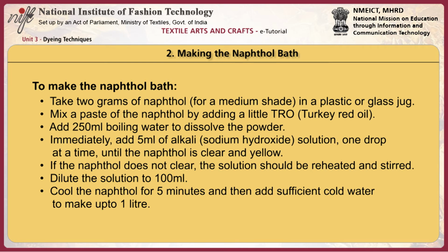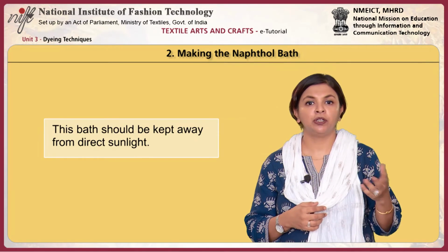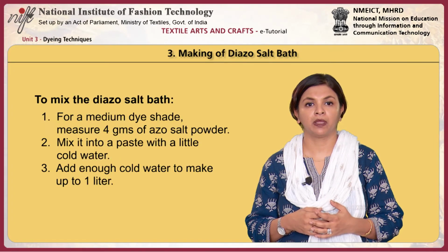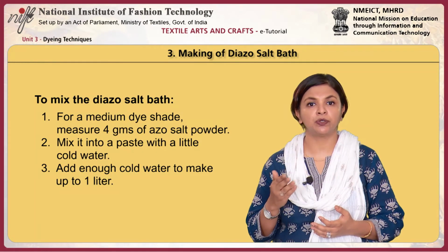Dilute the solution to 100 ml. Cool the naphthol for 5 minutes and then add sufficient cold water to make up to 1 liter. This bath should be kept away from direct sunlight. To mix the diazo salt bath.